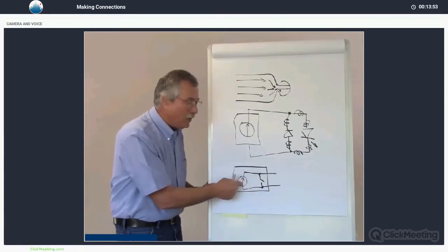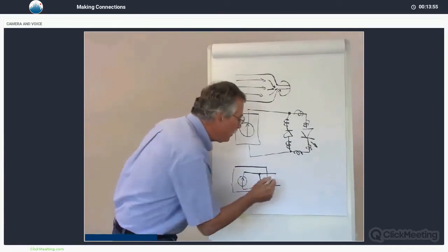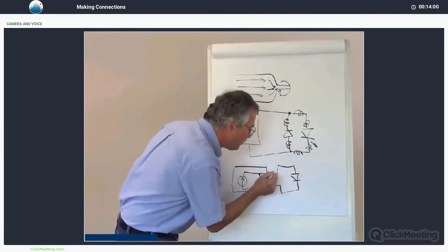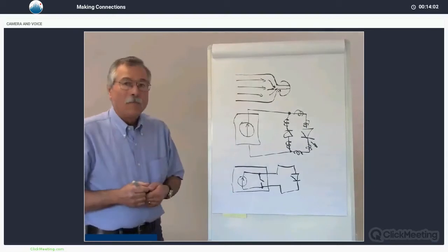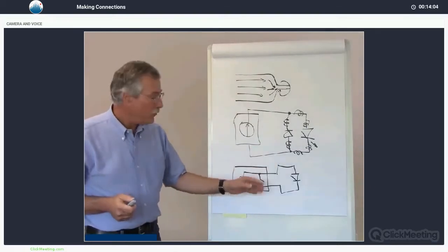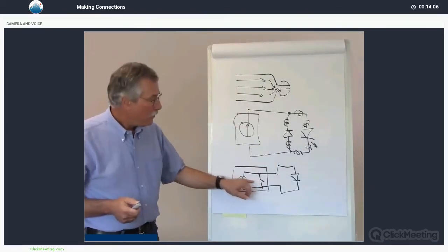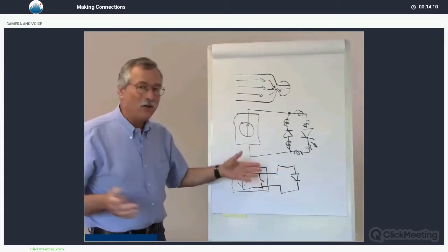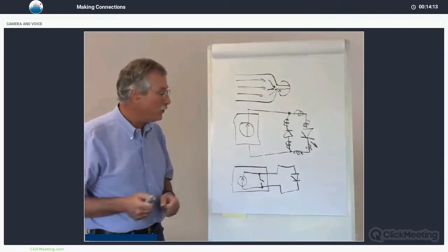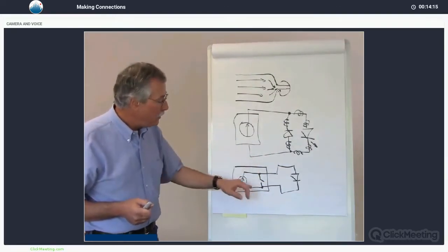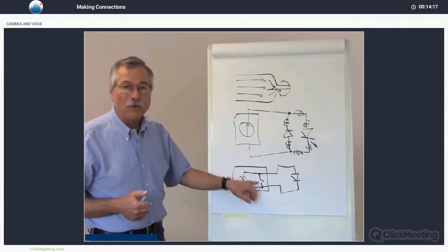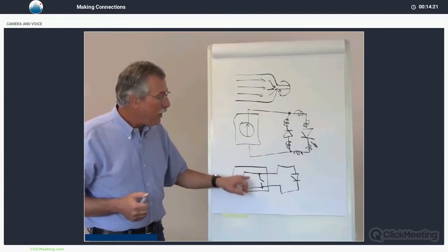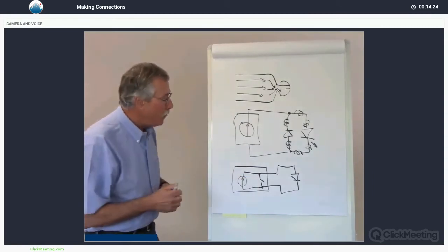When we open the switch, we allow the current to now flow through the laser diode. When we wish to end the pulse, we close the switch. Current now flows in this loop, and it avoids the laser diode, so we have now created a very fast-acting pulse, fast rise time, fast end time. This is sometimes called a shunt or a crowbar. It's actually a transistor, not a mechanical switch. And it's a way of getting very fast pulses.